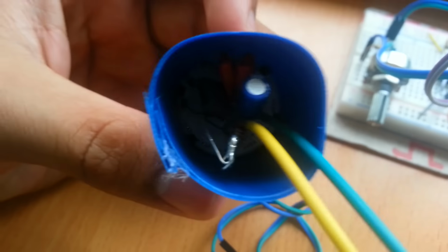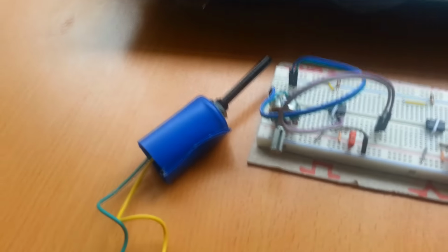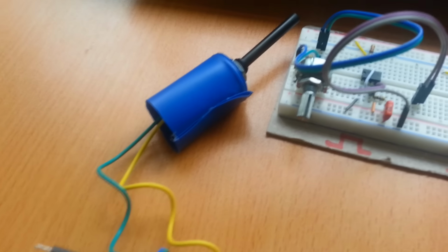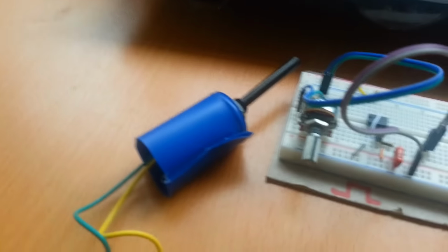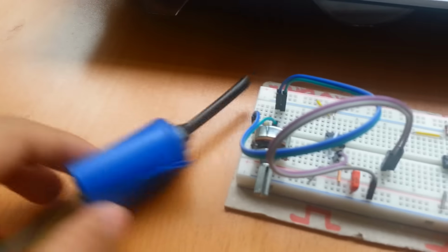We put 6 capacitors, and if I move the switch, I will get a different connected capacitor. Each capacitor starts from 1 picofarad, 10 picofarad, 100 picofarad, 1 nanofarad, and so on till we get 1 microfarad, and each one of them will give me that power-of-10 interval.